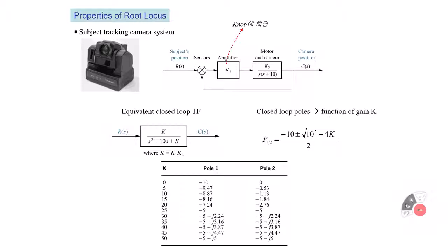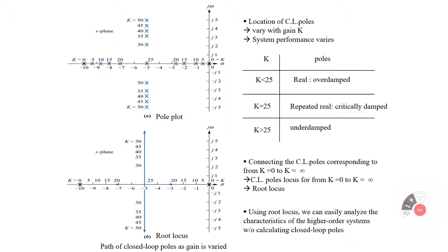Yes? And this is a second order system, so there must be two closed loop poles. 맞지? So look at this. Depending on the values of K, 0, 10, 5, my closed loop poles, this. Okay? And I'm gonna plot them on this complex domain. 복소 평면에다가 저걸 내가 표시를 했어. So, look at this. Here, 0. 여기 뭐가 있어요? Hey, this black X. Well, this X represents the pole. Okay? And circle represents the 0. Okay? And as you see, this and that is the closed loop pole when K was 0.